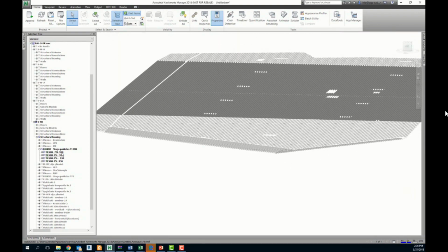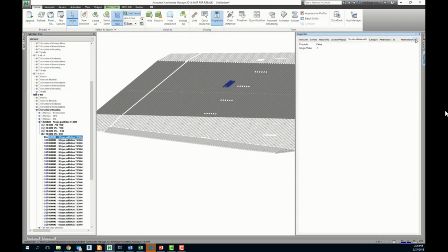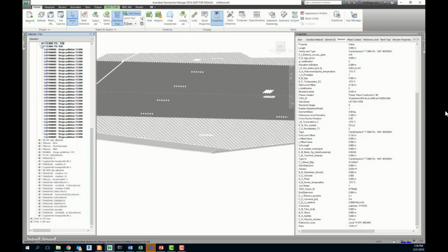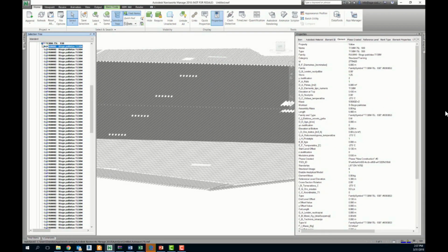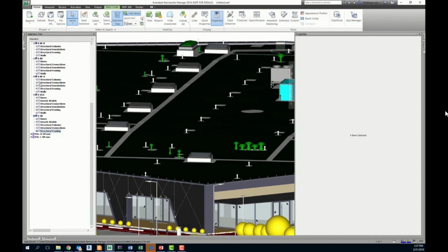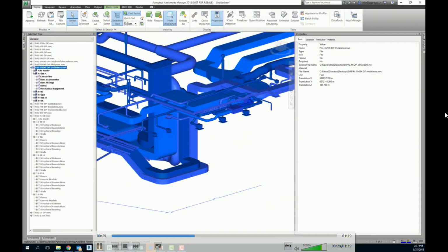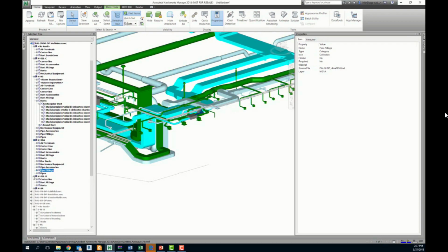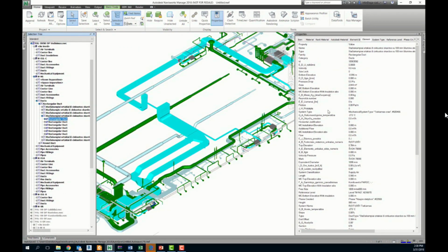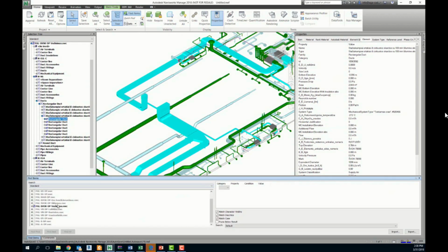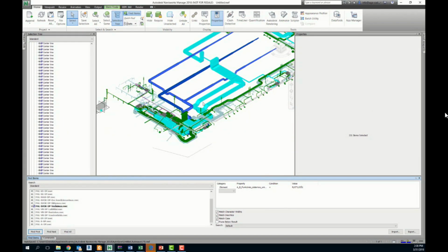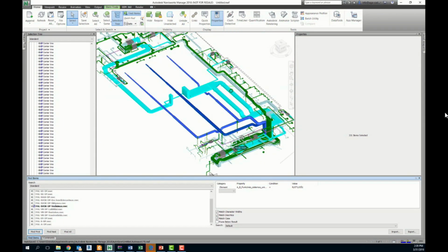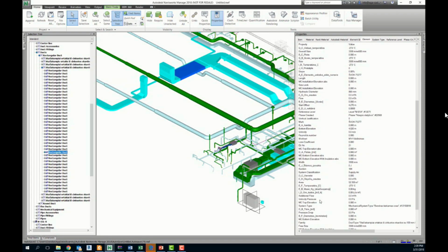But the principle is that when we export it from Revit, you get the tree with the layers, with the components, based on the types. And if you import the IFC file into Navisworks, you will have a completely different picture. So we had issues with parameters and with their structure. So navigation was very complicated.